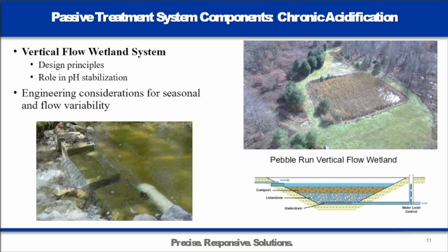And these are standard vertical flow wetlands. You guys are probably all familiar with them. Very simple: you have a 3-foot layer of high calcium limestone, a 2-foot layer of mushroom compost, and a 1-foot freeboard on there, utilizing an agri-drain outlet and a 100 by 100 basin.